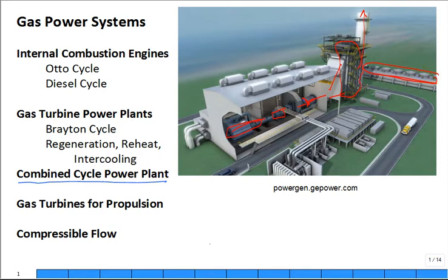They're mechanical draft. There's a big fan that draws air through, and they have water that's splashing down, and so it's an evaporator that provides the cooling. Typically, that's not the same fluid that's going through the steam turbines. It's probably a separate heat exchanger somewhere in here, where you have 2 water loops to transfer the heat, because a lot of this water is evaporating. It has to be replenished. It's still kept clean, but not to the level of the chemistry that's needed for the water that goes through the tubes in your steam generator and boilers, as well as through the steam turbine itself.